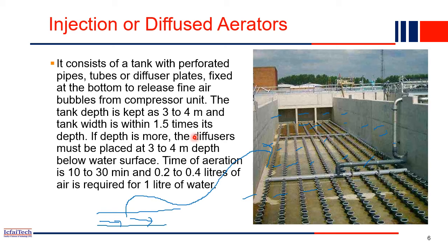Again, depending on how much quantity of water we have to treat, the size will again vary. And the tank width is 1.5 times its depth. So the width will be 1.5 times the depth. If depth is 3 meters, then the width will be 4.5 meters.